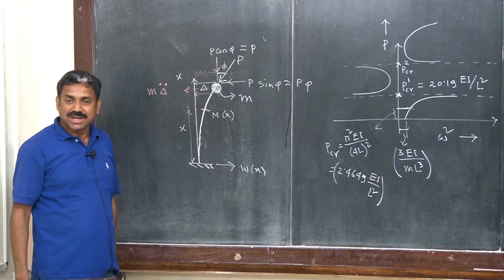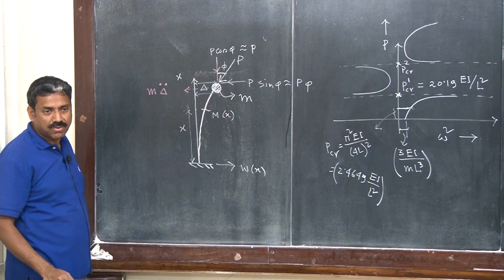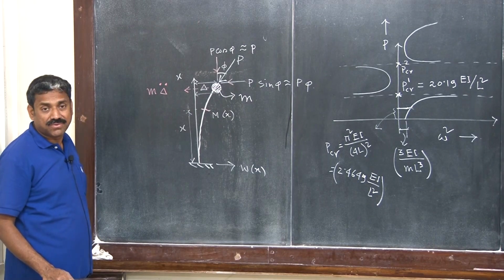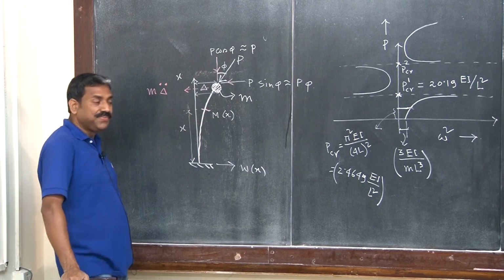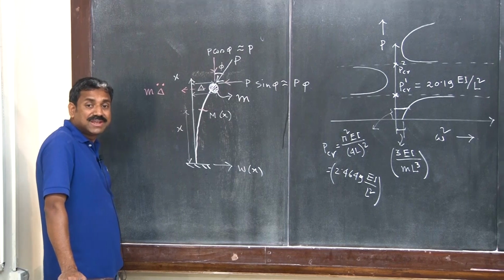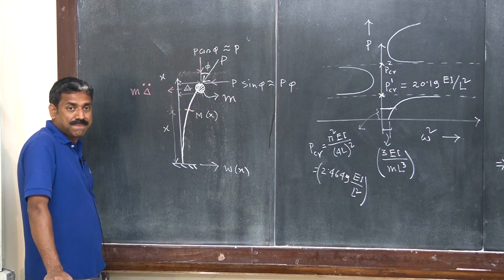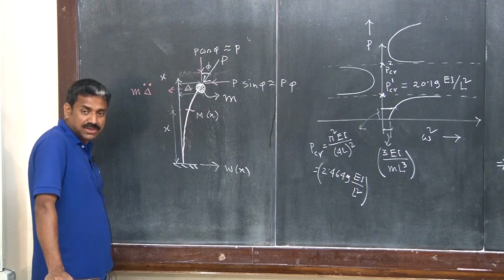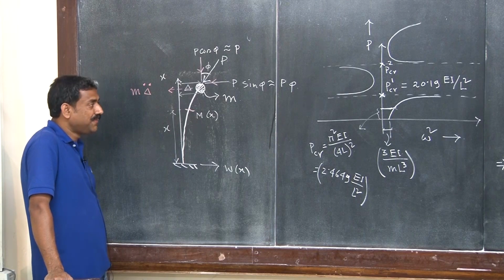That is why the follower force is non-conservative. Do we understand why the follower force is non-conservative? Because a component of that follower force, which in this case is in the transverse direction, basically acts on the lateral deflection to result in work done and thereby dissipation. That is why the follower force is a non-conservative force. Clear?